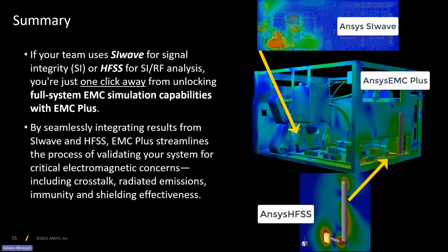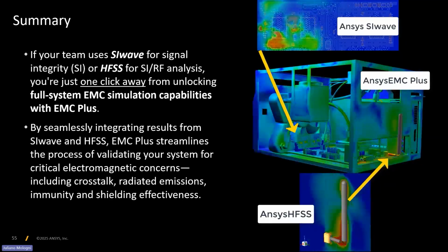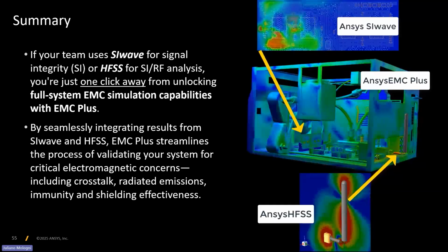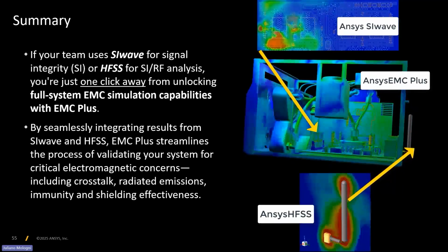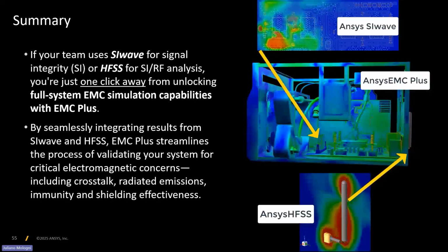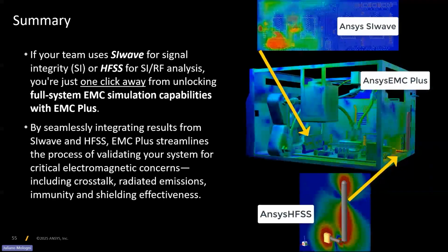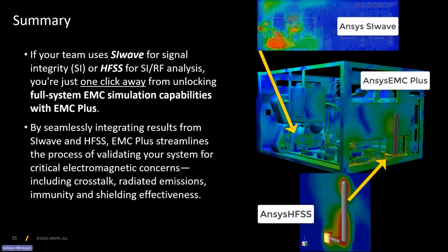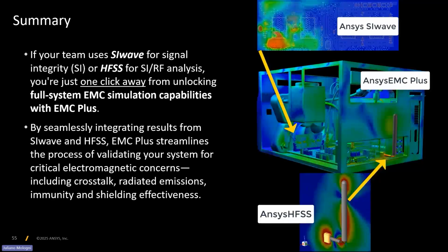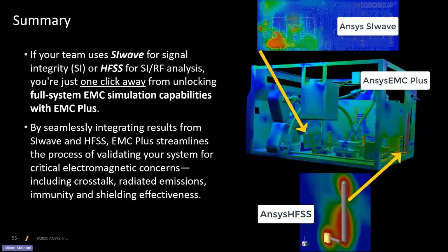But sometimes that's not really necessary. When you're using a numerical technique like FEM, where you have to mesh all the details, then you have to clean and adapt the geometry. But for EMC Plus, they have a very tolerant meshing algorithm, just like any FDTD tool, right? You don't have to simplify your CAD model thoroughly. But yeah, you have all that capability from Discovery, legacy SpaceClaim. It's already built into EMC Plus.